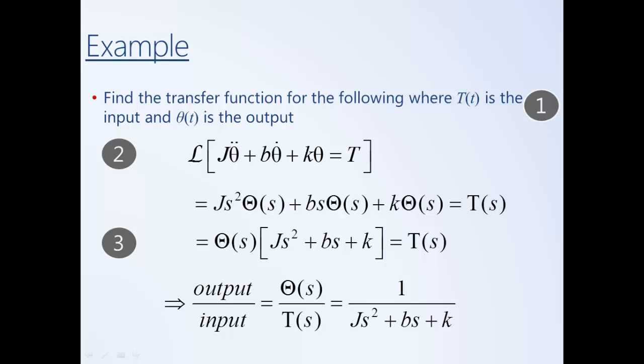And so looking at this, we notice a few things. One, it doesn't depend on the forcing input at all. This represents the drive line no matter what type of input torque we have. This is what the drive line looks like, whether or not the torque is applied in a step, whether the torque is applied sinusoidally. So the transfer function doesn't depend on the form of the forcing input. We can also see that since we assumed 0 initial conditions, it doesn't capture the effective initial conditions on the system.